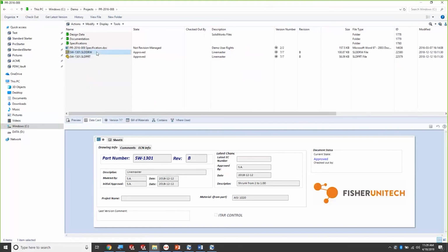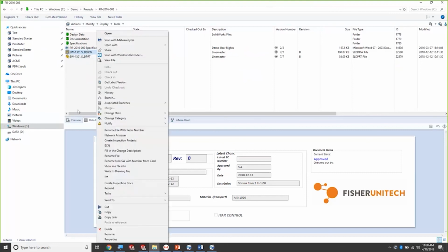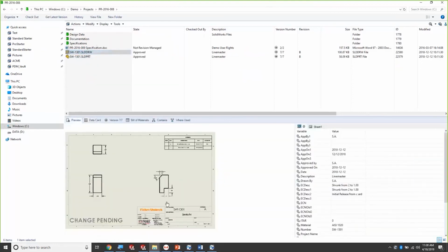There's a technique inside of PDM that you can actually use to create a historical link between files. If you go into SOLIDWORKS and do a SOLIDWORKS file save as, you're creating a brand new widget. It has no link to anything. In certain instances, though, it would be nice to know that I'm creating a brand new part based off of this part right here, and I want the two files to have some sort of a link. I want to be able to trace the history. Where did this thing come from?